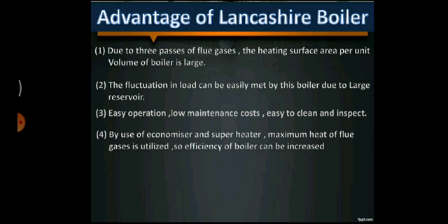It is an easy operation, low maintenance cost, easy to clean and inspect. Fourth, by use of economizer and superheater, maximum heat of flue gases is utilized, so the efficiency of the boiler can be increased.